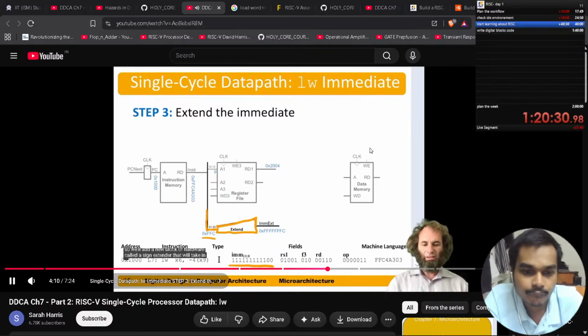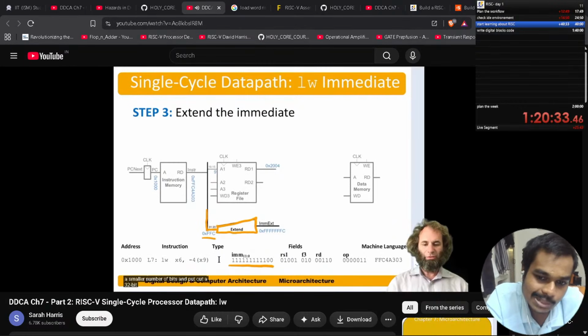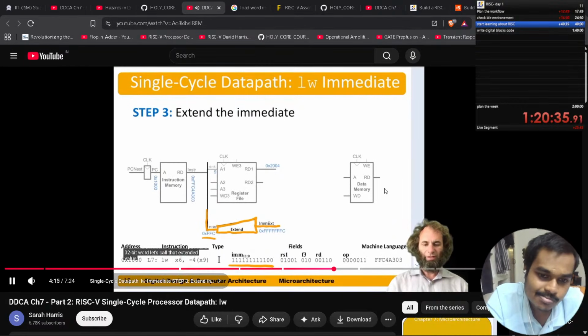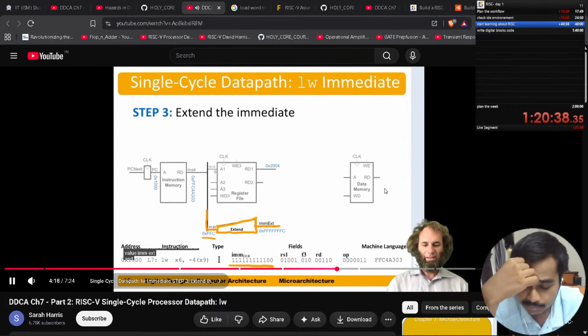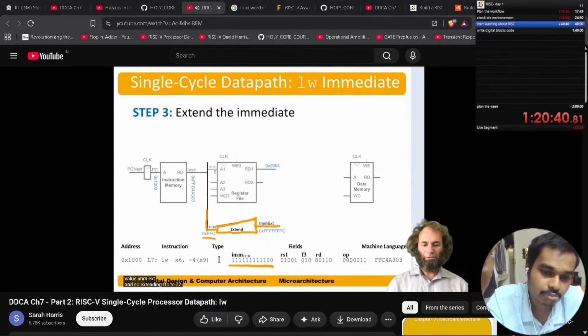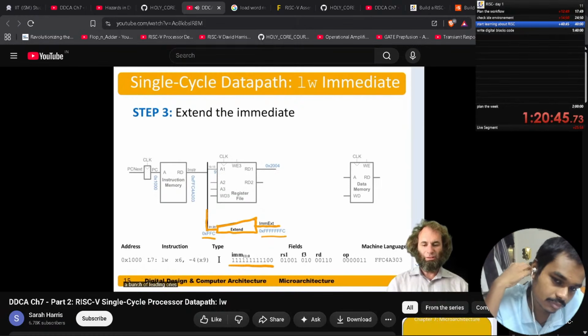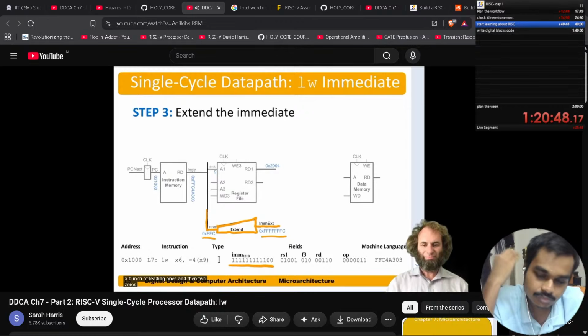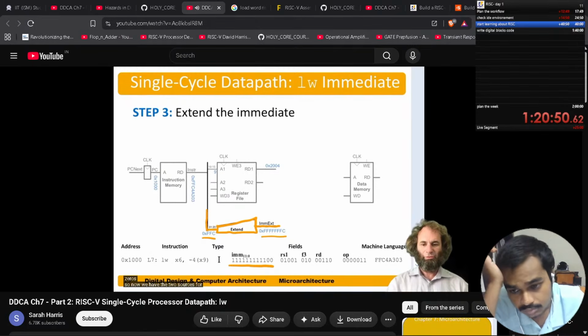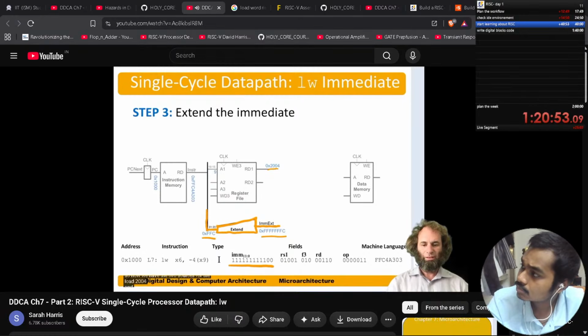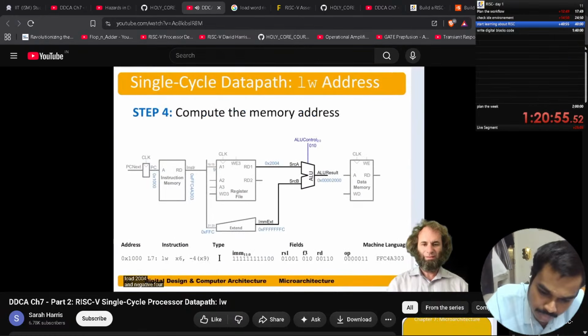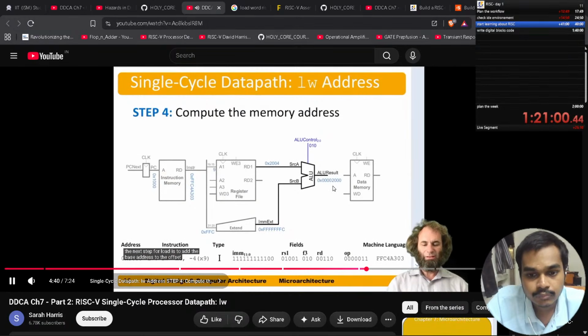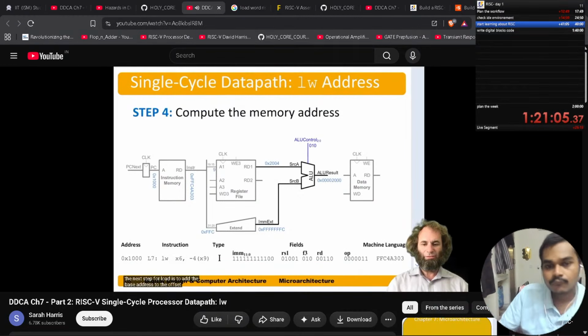That will take in a smaller number of bits and put out a 32-bit word. Let's call that extended value IMMEXT. And so extending FFC to 32 bits is FFFFFFFC. Bunch of leading ones and then 2 zeros. So now we have the two sources for the load, 2004 and -4. The next step for load is to add the base address to the offset.